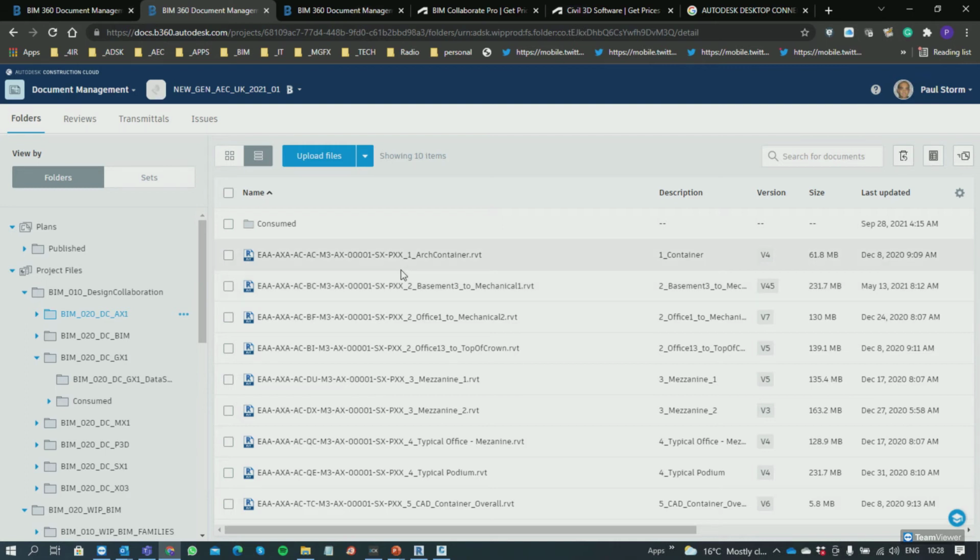It makes it easy for Revit users to understand because Revit is not backwards compatible. And in the same way, these cloud projects are not backwards compatible. You can always upgrade or update a project onto a newer version of Revit, but you can't go back onto an older version of Revit. So make 100% sure that when you initiate your first file on your project, it is within the year that you would like to work.